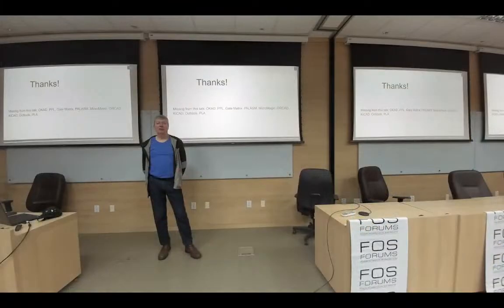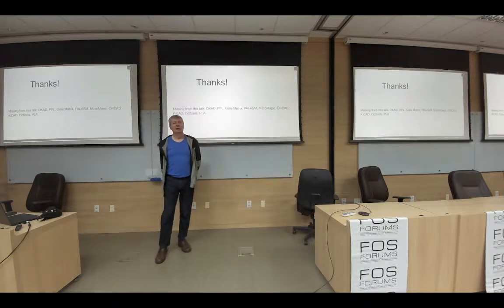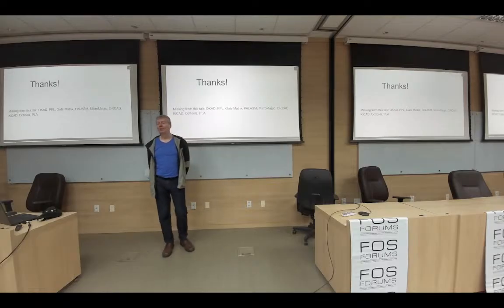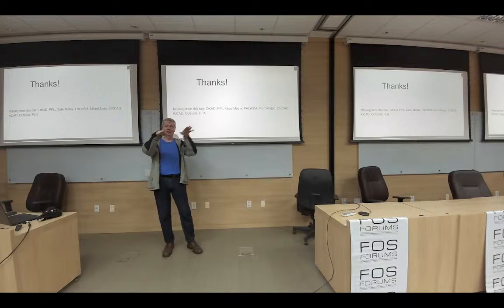Yeah, there are features missing. KiCad has come a long way. I've looked at it almost since the start, and one of the advantages is that there are no limits. There are tools that will give you a free version, but only if you have 2 layers, only if it's so many by so many centimeters or whatever. Otherwise, you have to pay the $10,000 version, and I actually have compared them. But some of the very high-end tools that are very expensive, for example, will simulate the electromagnetic interference. So you know that, oh, this track here is generating this waveform. I mean, you can do this with open source tools, but you really have to know what you're doing. So it's not for everybody.